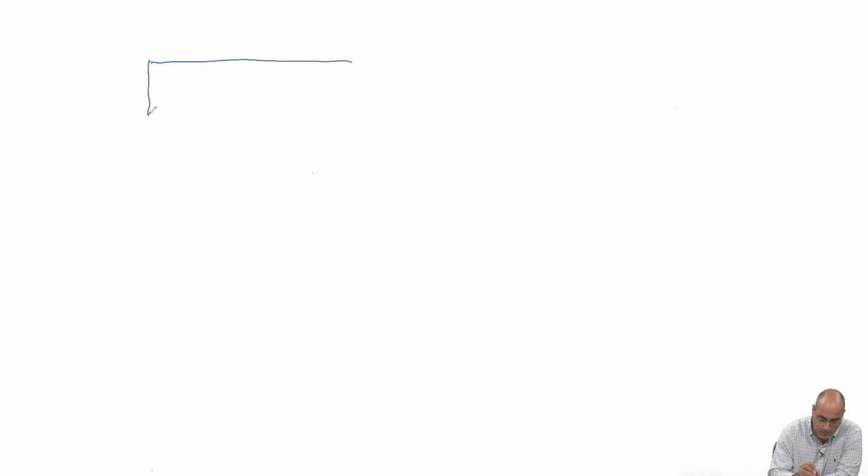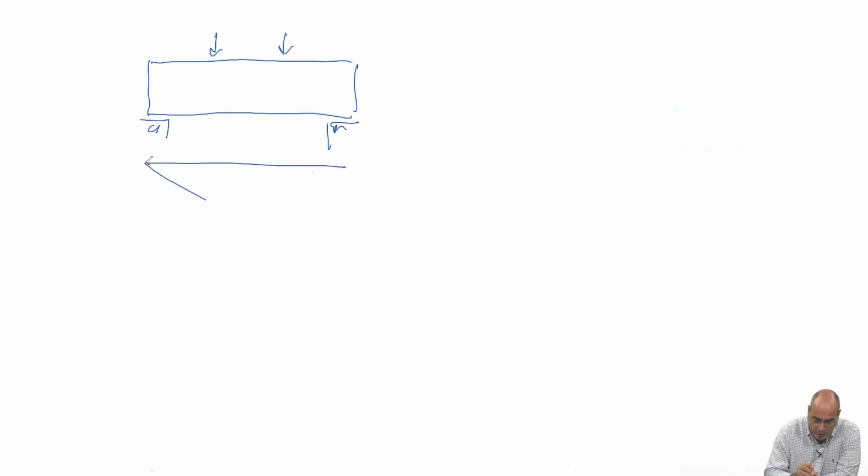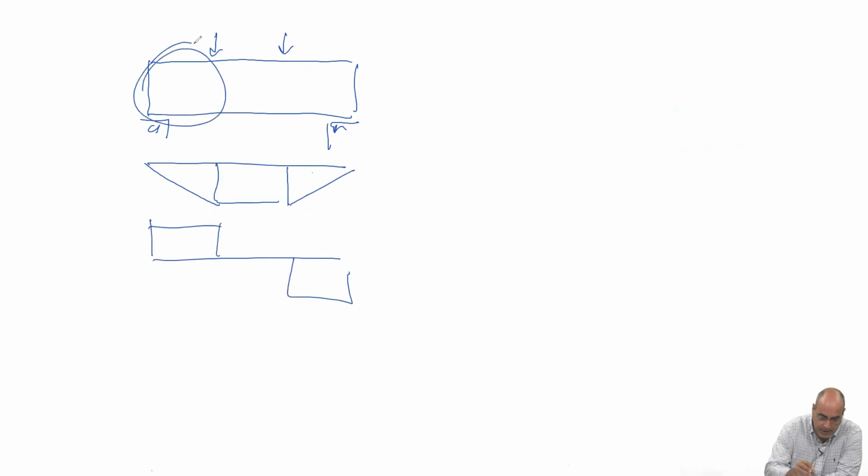So as I was saying, Ritter and Morse did tests on beams like this. This is the support. There was a load here. So that your bending moment diagram is like this, and your shear diagram is like this. So in this region here, you expect to be shear critical.